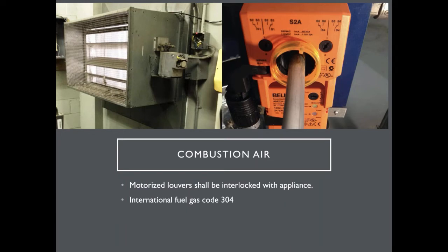One of the things that we see is the combustion air louvers on a lot of the commercial jobs. And it says the motorized louver shall be interlocked with the appliance, and it's under the International Fuel Gas Code.